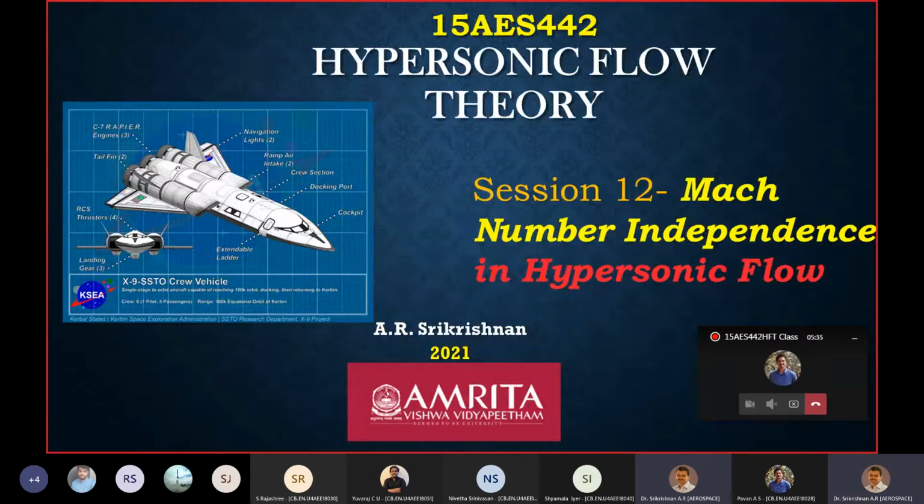many of the aerodynamic coefficients, when they are expressed as non-dimensional parameters, can be shown to be practically independent of Mach number in hypersonic flows. Which means that once you have some value for those coefficients, which you have got at, say, lower hypersonic velocities, you can approximate them to hold for even higher values of Mach numbers, because the expressions by themselves are Mach number independent. So that's what we mean by Mach number independence. We'll look at how we arrive at this conclusion.